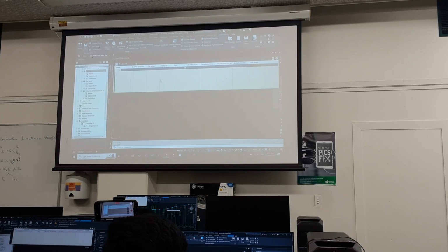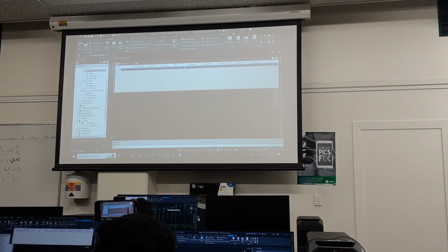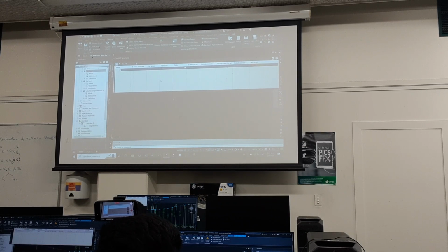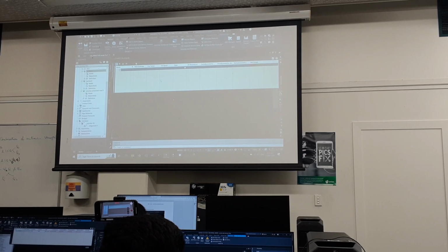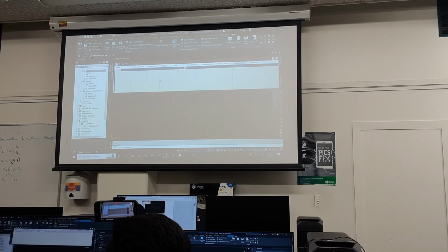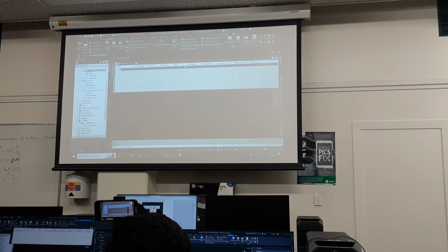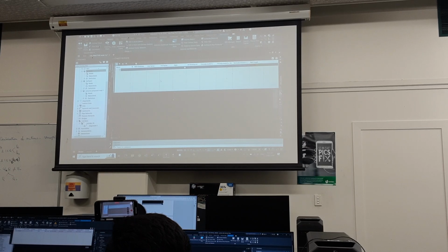The assignment's asking you to balance it as best as possible. It doesn't say to the nearest X metres, but if you take 6 cubic metres as being a truck, I think probably an acceptable amount will be a few truckloads. A not so acceptable amount might be something like 20 or 30 truckloads. You're probably pushing it a bit there with your balance. I got mine at 2.6 metres first go. So 2.6 metres is half a truckload. That's pretty good. First go. I mean, you have to adjust it. You drew it perfectly.